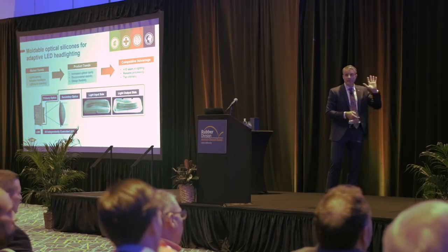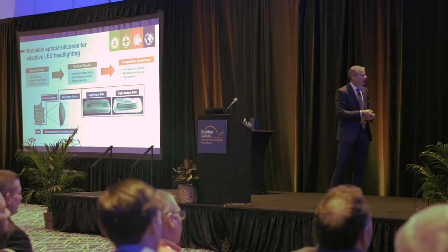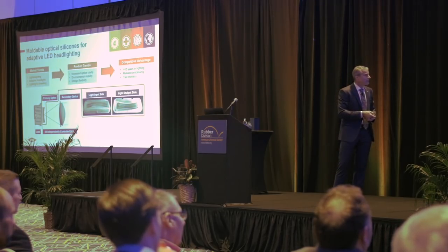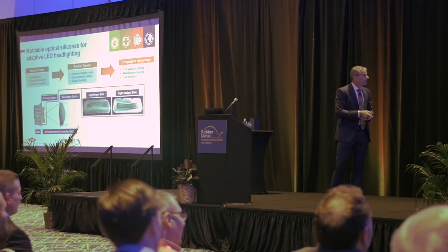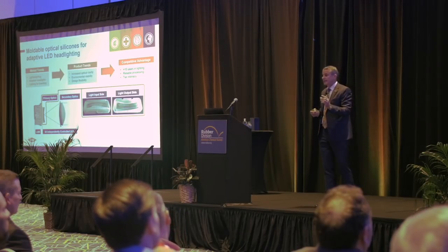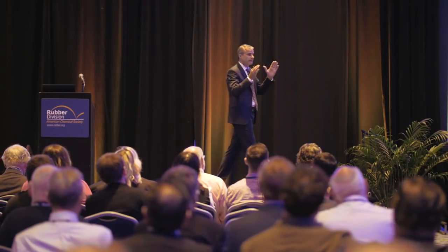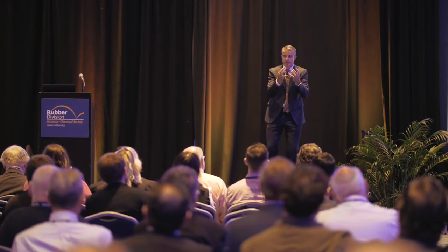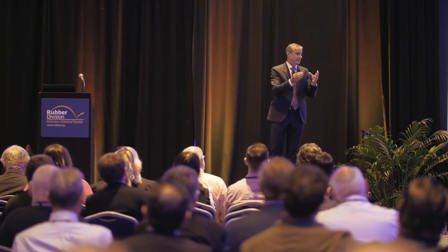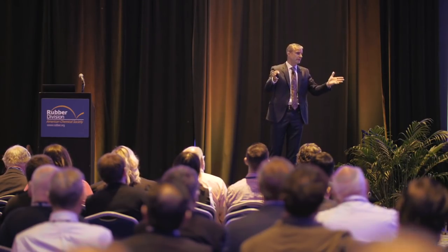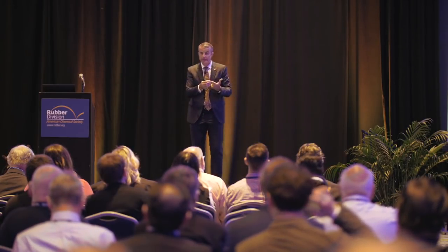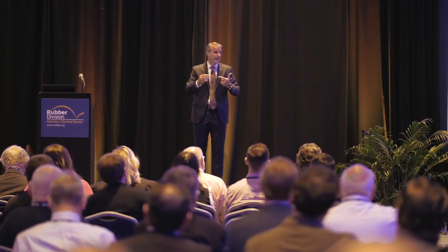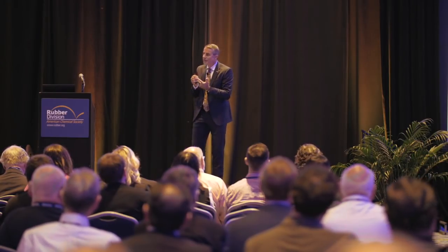This is what you see from the front of the car, right behind the secondary optics. And then on the back of this lens here is the light input side with these 84 different light pipes. Now think about this. This assembly, this one part, has to last for 10, 12, 15 years, ideally. It has to be perfectly weatherable. It can't yellow, it can't get brittle, it can't get anything. It is very, very fragile.